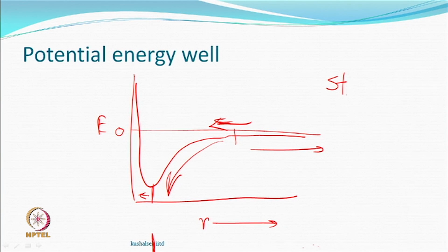What you are doing in drawing is, of course, putting in your energy, but simultaneously you might be doing an exercise to bring some molecules together, and once they come together, then they know what to do, and they are also connected with each other, they will pull the other molecule, the other part of the atom also comes near. So, finally, sometimes we see that is what happens. This is what we call stress induced crystallization.